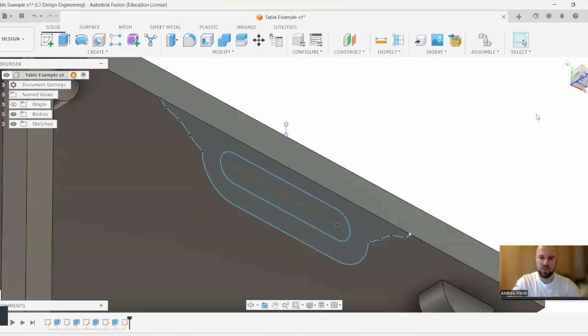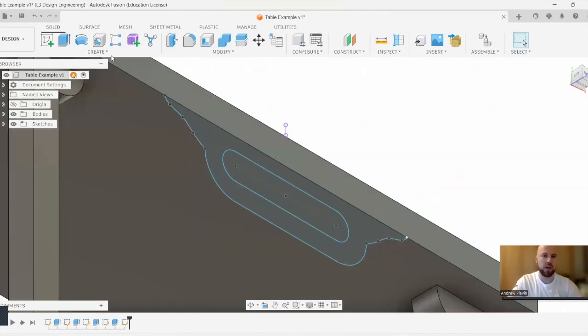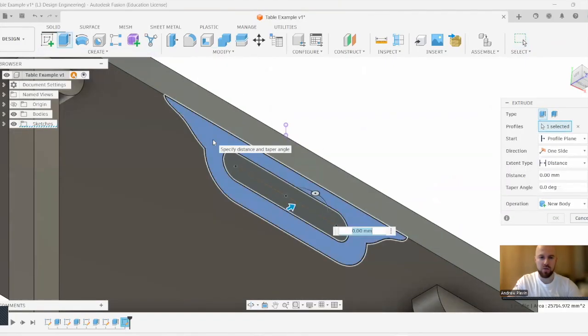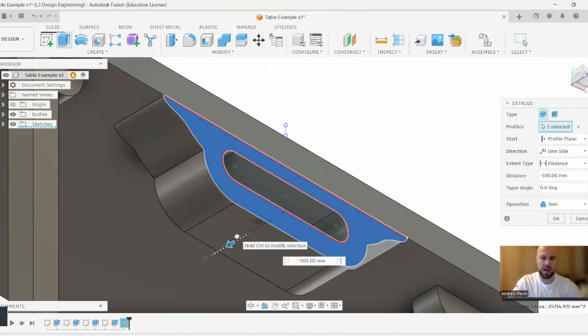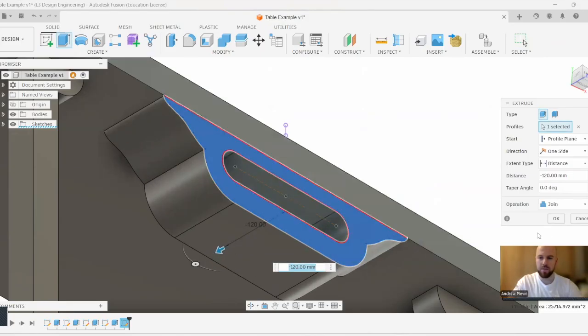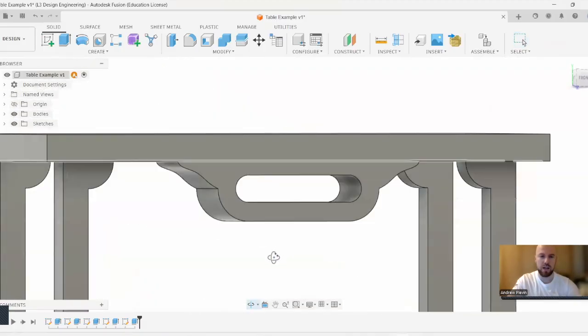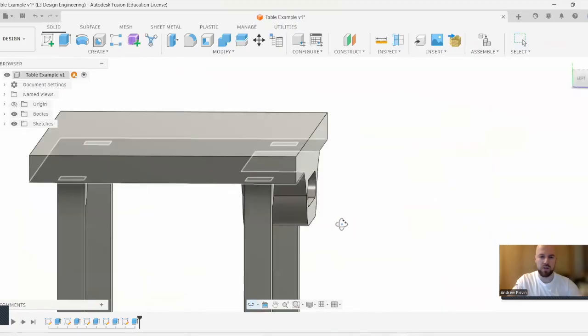And then to make this 3D, we're just going to use that extrude tool once again. Select just that outer profile, extrude it back by, let's just go with 120, and just click that OK button just there. Then one last step to do, just so we don't go to place our phone or whatever else it is inside this and it just falls through the other side. We're just going to close this off slightly.